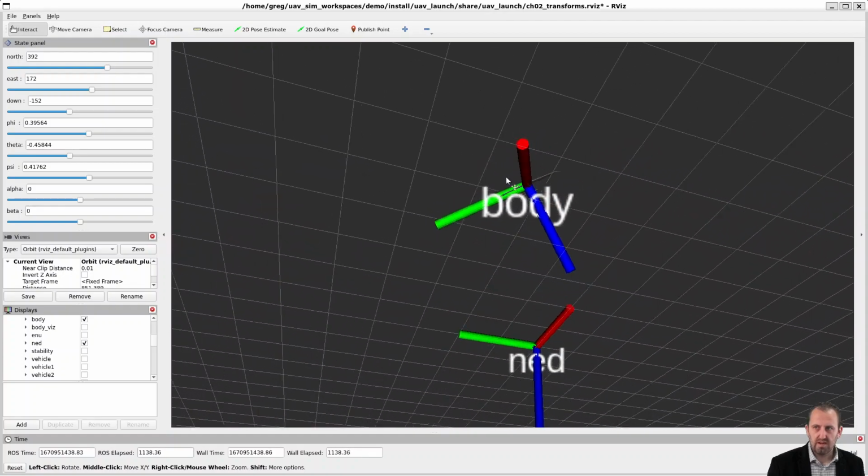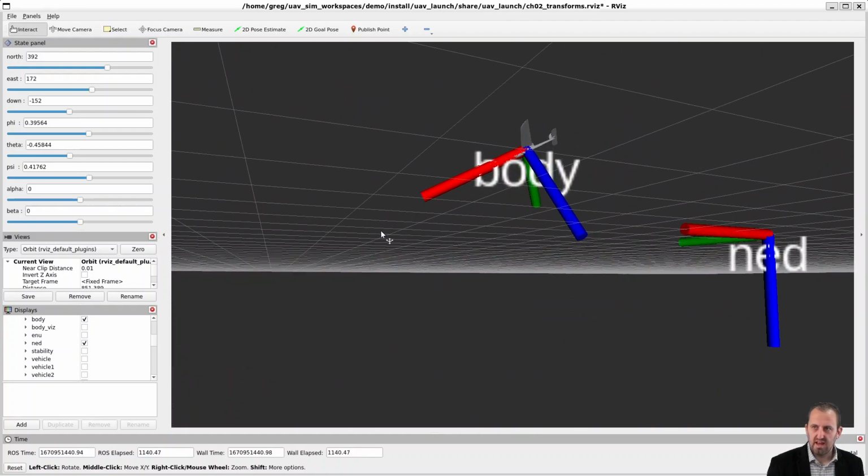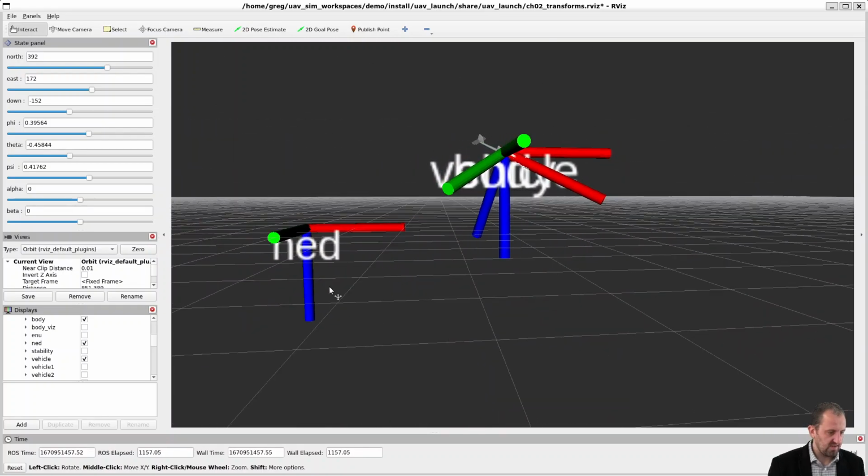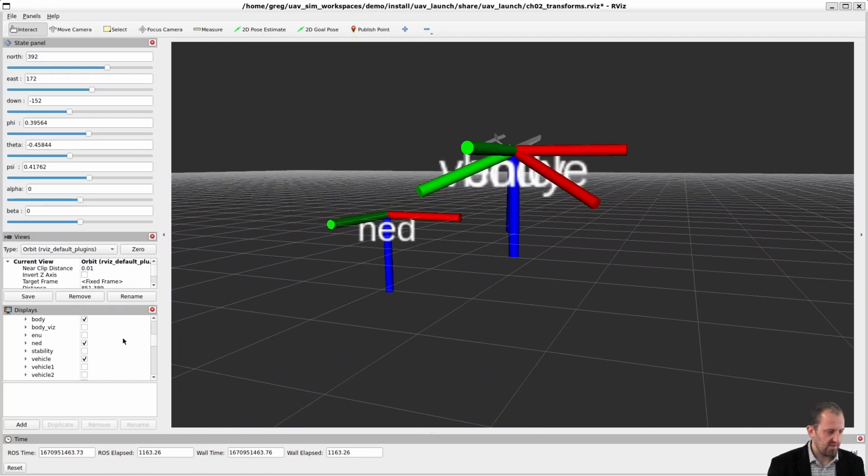And if we look at the bottom, that z-axis is pointed directly out the belly of the aircraft. Okay, so that defines all of the rotations we need to get from the vehicle frame, which, if we draw that back up, is aligned with the NED frame. It's just been translated. And the body frame is aligned with the aircraft.